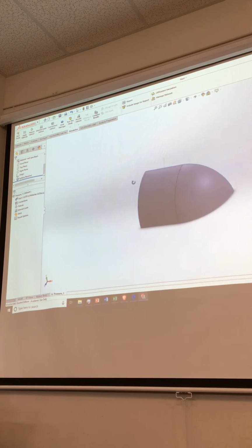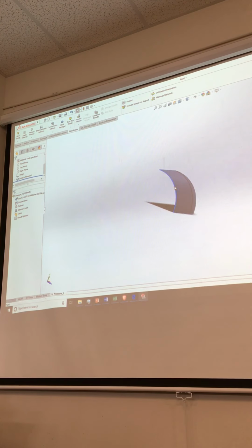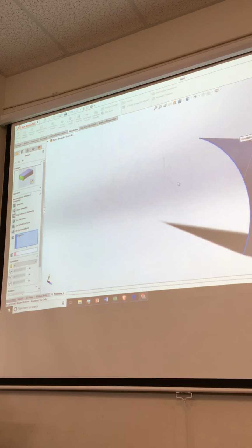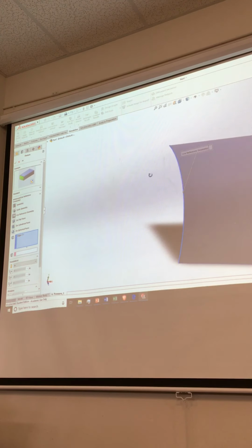And the way we do symmetrical boundary conditions is I'll pick on an edge like this one over here. It's behind itself, and I can do advanced fixtures, right? And it's already selected the edge. And then I'm going to do some geometry here. Select my geometry for this guy. And I really badly for this one want to pick the right plane. Okay? And I want to pick the plane in which I'm going to fix the out of plane displacement.